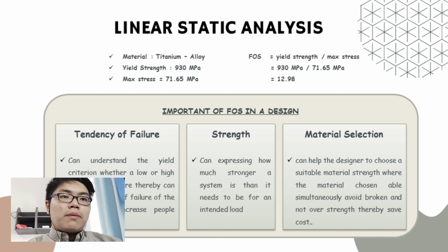The last one is material selection. As we know, the FOS calculation depends on the material yield strength and the maximum stress. If the FOS calculated is too high, the designer can choose another suitable material to reduce the cost.